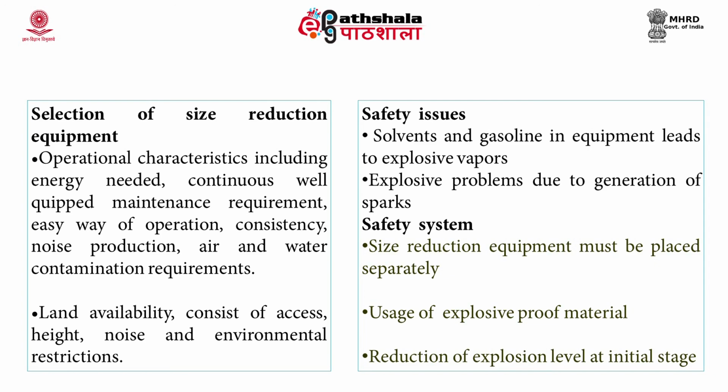As a matter of safety, the size reduction equipment should always be placed separately, and you should use explosion proof material. To conclude, today in this lecture we have seen what is size reduction, and what are the different ways by which we can do size reduction. We have also seen the importance or significance, or why we actually need to do size reduction. We have also seen the different mechanisms which are involved in size reduction and the various laws governing size reduction. Finally, we have also seen the criteria which you will look into while selecting a size reduction unit.